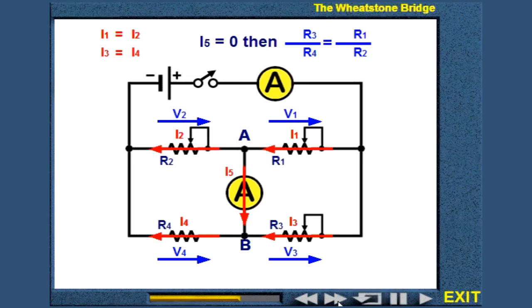Using the equation obtained, it is easy to find the value of one resistance when the other 3 are known. For example, the resistance of the fixed resistor equals the following. Use this equation during the experimental session to calculate the value of the fixed resistance. However, you must adjust the variable resistances if you want to obtain zero readings on the sensitive multimeter display.